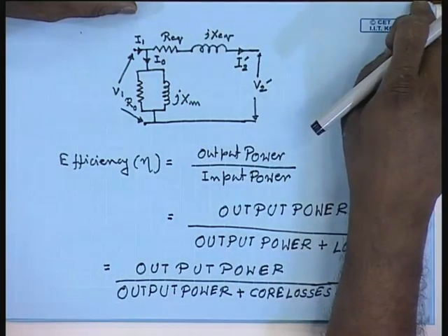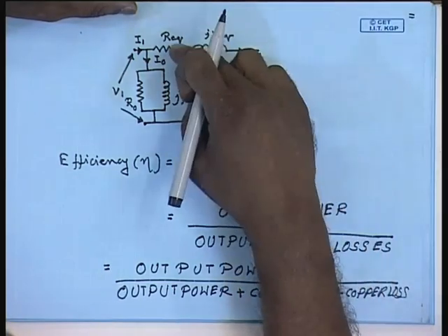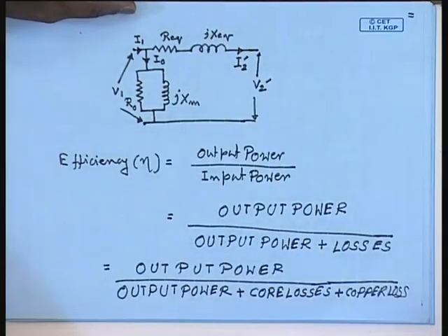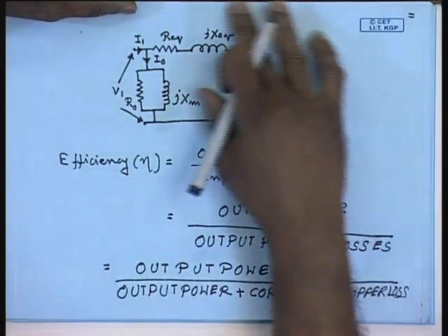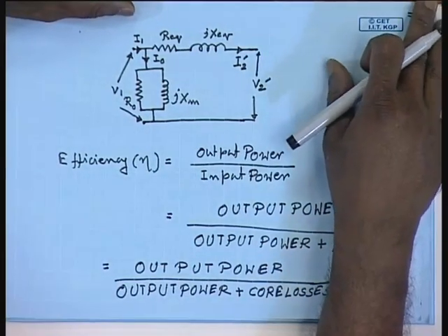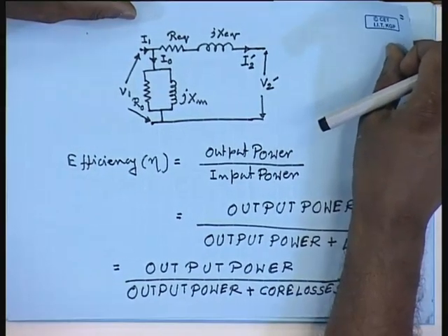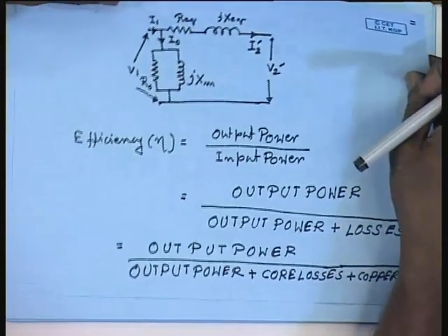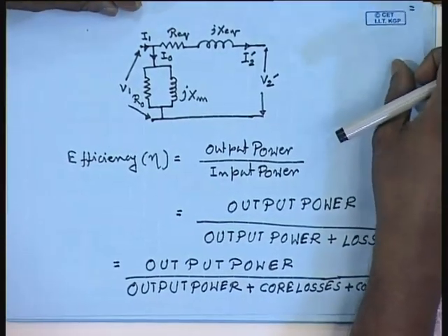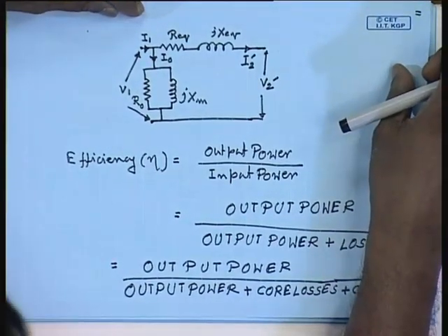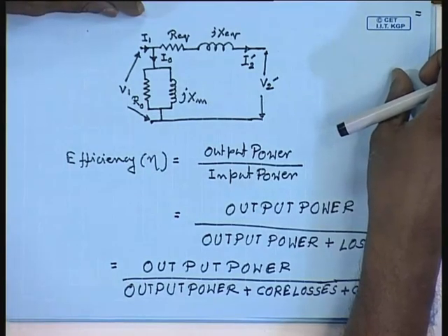So, the wattmeter reading actually represented the copper loss. Now, short circuit test is usually done at the rated current, therefore, the value we get is the full load copper loss from short circuit test. Similarly, from the open circuit test, we get the iron loss, which is independent of the load current and constant.